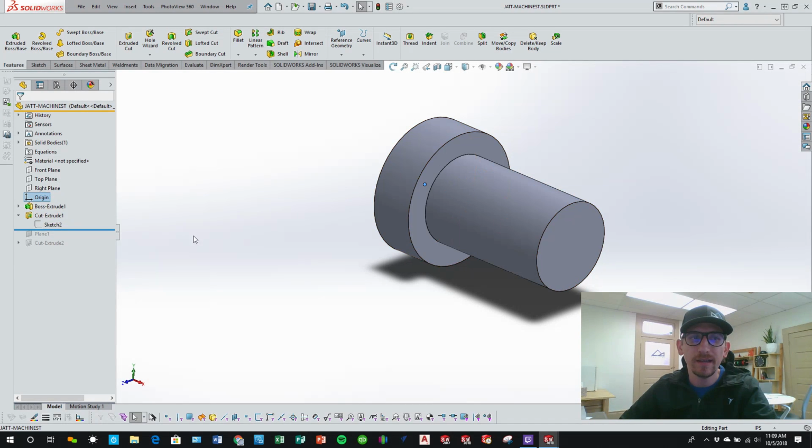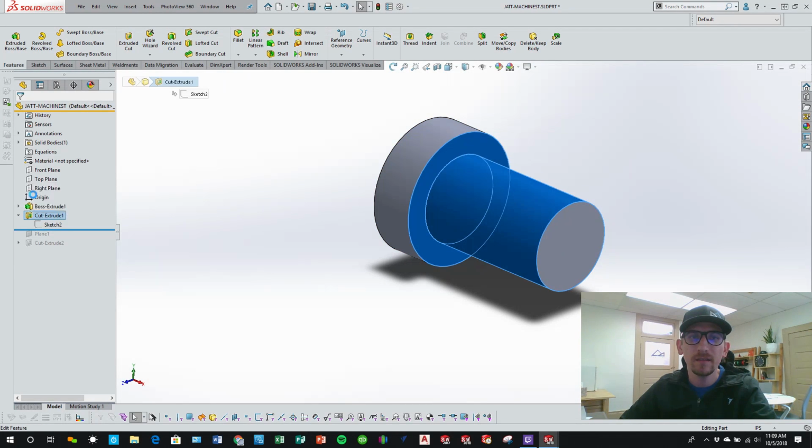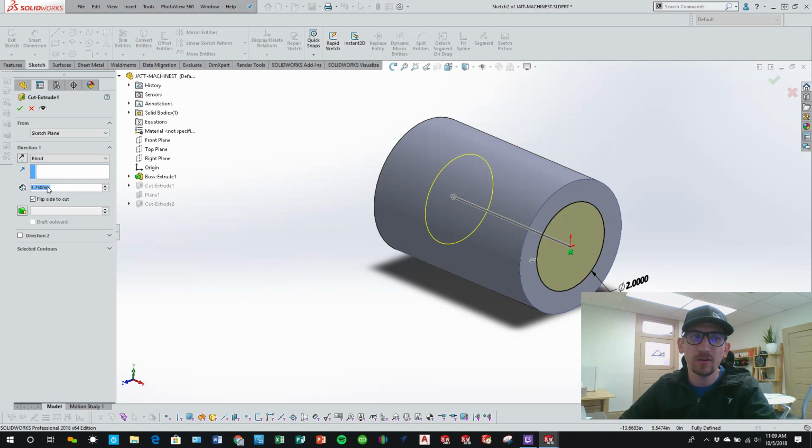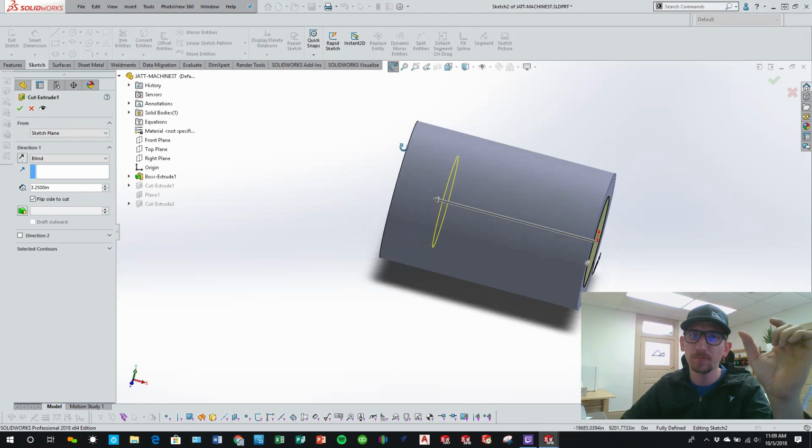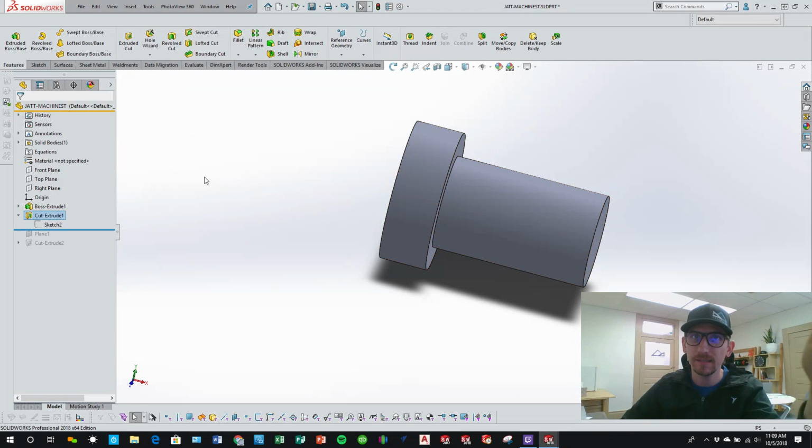So now that you say okay to that, next up, oh, and by the way, how I went about that cut is I told it to come in 3 1/4 inches, because based off of our very first part, I made it a 1-inch thickness. So I made it 3 1/4 depth.